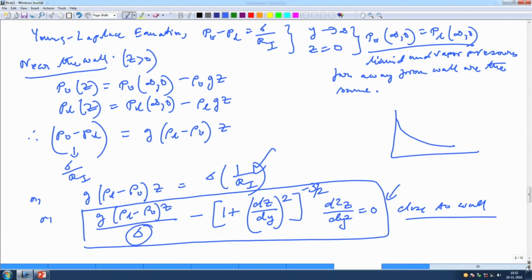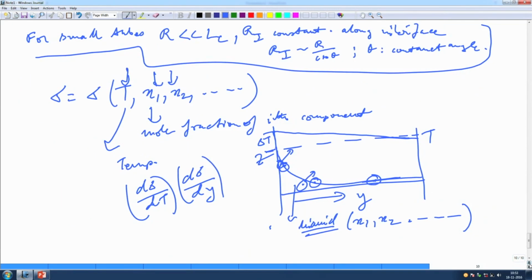When the surface tension is not constant everywhere, like in this particular case that we mentioned, there can actually be flows or velocities introduced within the liquid, okay. Between high surface tension and low surface tension, you have a difference in pull, right. So, this can drive a liquid flow.